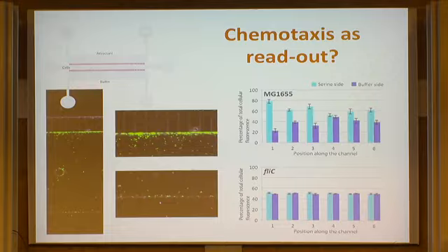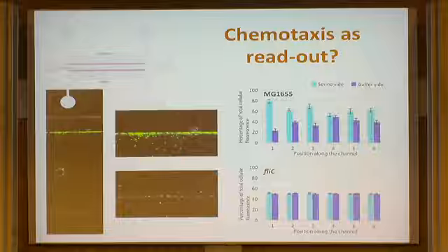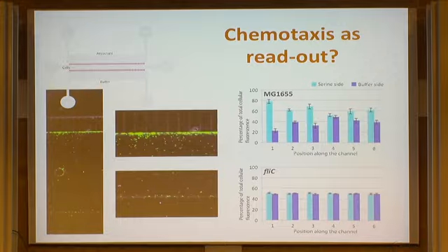I should be able to tell you, but the problem in microfluidics is, do you want to have the flow in cubic volume per second, or do you want to have it in 10 microns per second? No. 1 millimeter per second? No, not even. So this must be in the order of 1 micrometer per second. Okay, and these are flow lines, again, with a height of 50 microns. So it's very, very small flows, because otherwise you push the cells away and you cannot see the chemotaxis.